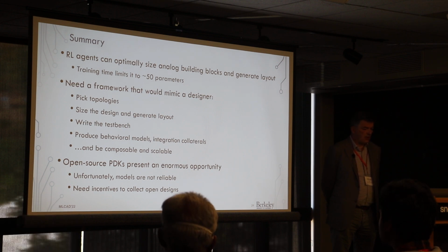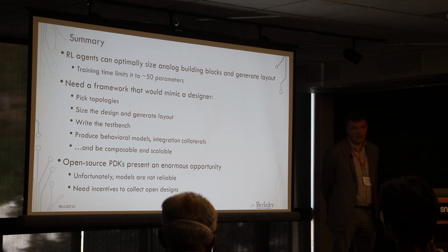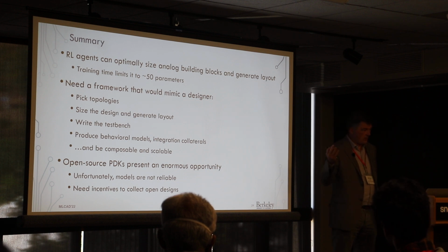RL agents can optimally size analog blocks and generate layout. The challenge here, computationally, is that this is limited to about 50 parameters or so for practical training time. Maybe a little bit more if we try to deploy a little more fancy RL techniques. But we are talking about exponential. 10 to the 50th is a very big number, even if we shave off 30% of it.